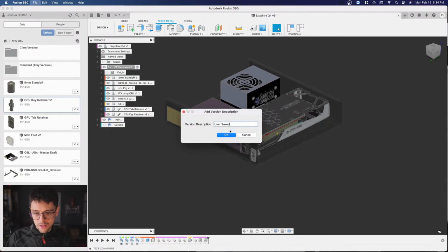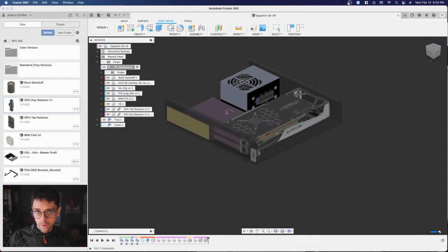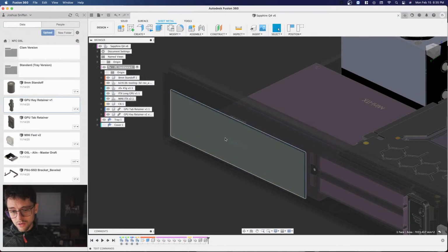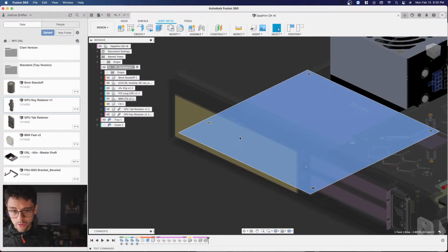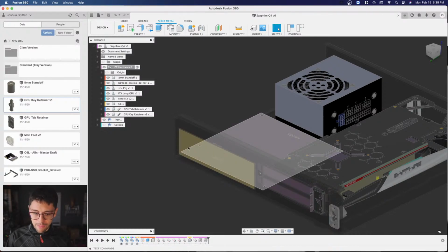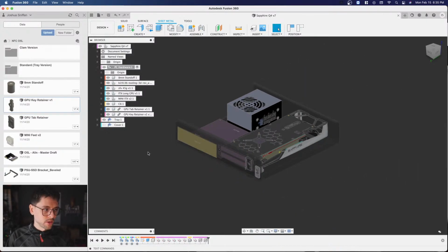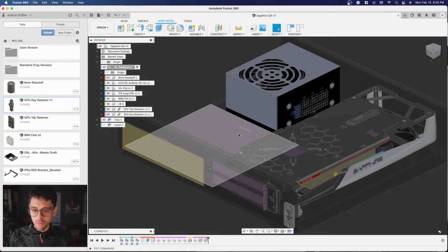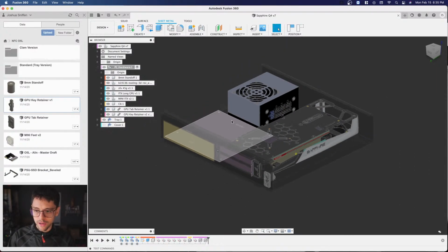Okay, this is great, guys, because now we have our clamshell design. We have our mounting for our motherboard, our standoffs. We know where the I/O is going to be. Oh, that's another really difficult thing to know. How do you know where to put the I/O cutout in relation to the motherboard? Well, you follow the ATX standard guidelines, which you can Google, or you can download the 3D model that I have on my Patreon or in this YouTube channel. So that's how you know the relationship between those two. But otherwise, it's a difficult thing to figure out.